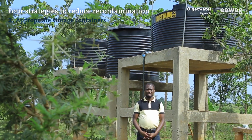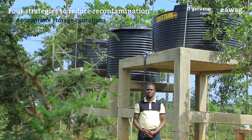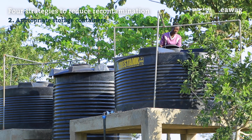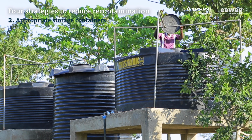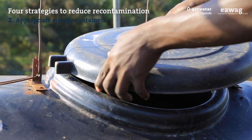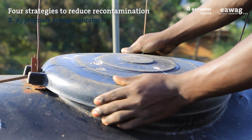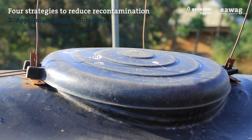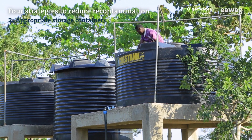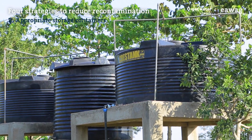Secondly, appropriate and hygienic storage containers are very important to reduce the risk of recontamination. For the clean water storage tank, this means that it is important to always keep the tank's lid closed to guarantee that no contamination enters from the outside. Additionally, the tank should be disinfected once a month. This procedure is described in a separate video in this series.